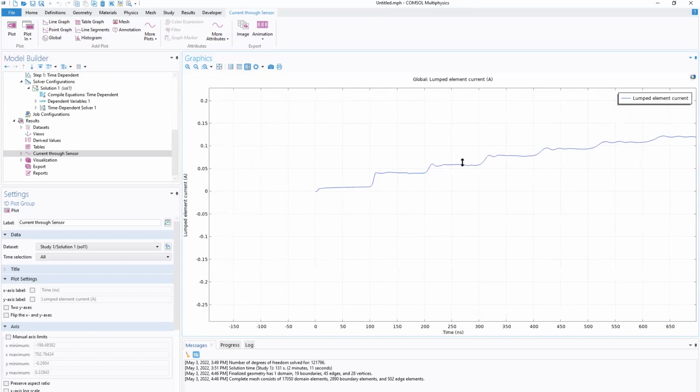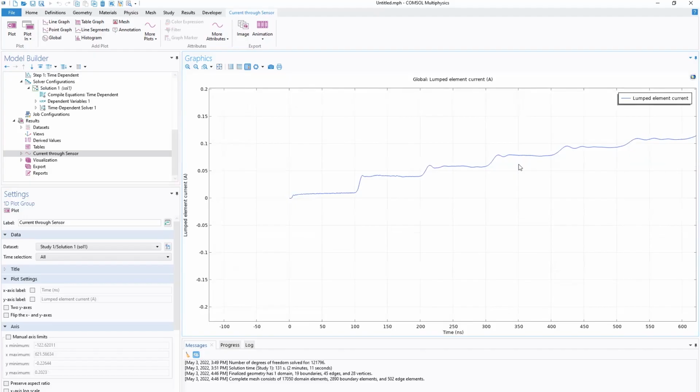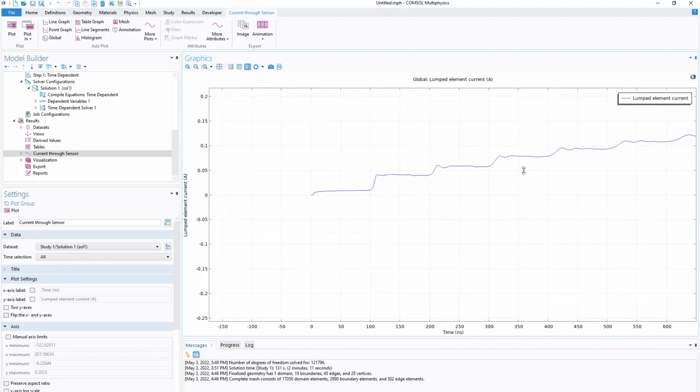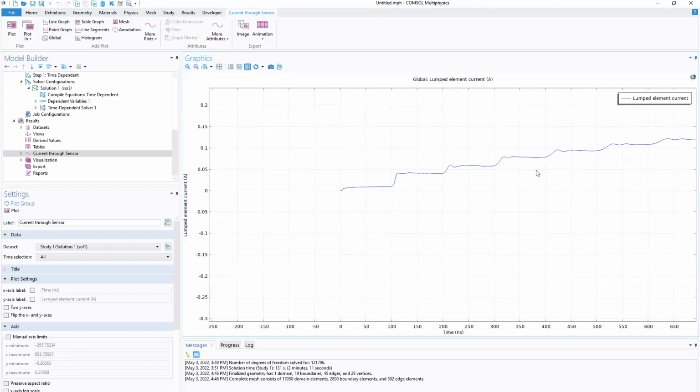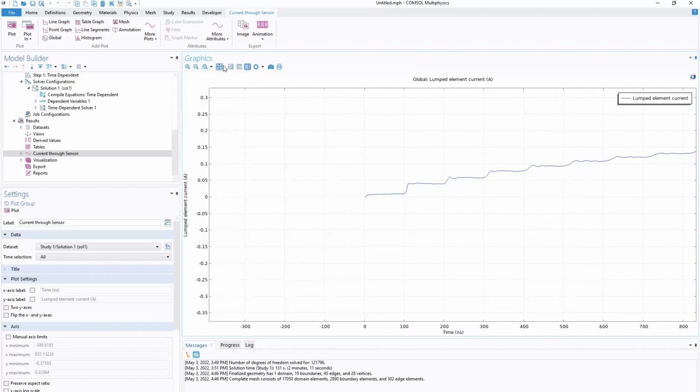And what we can particularly observe here is that from one plateau to the next, all of these sharp peaks are starting to get smoothed out and widened. And this is due to the loss and the dispersion in the model, and that has to do both with the receiver itself and with radiation away from the system. There is also signal getting radiated away.